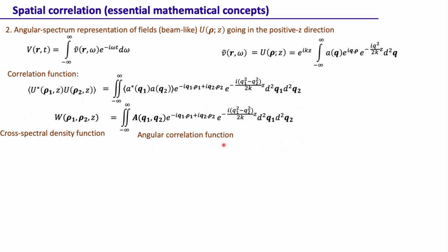And just like in the case of time, when we saw that the correlation function in time and the correlation function in frequency had a very nice Fourier relationship, which we then called the generalized Wiener-Khinchin theorem, and then the normal Wiener-Khinchin theorem, can we have something similar here? If you look at it, there is a relationship, but this is not exactly a Fourier relationship here.